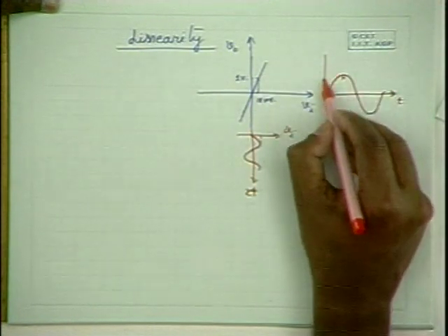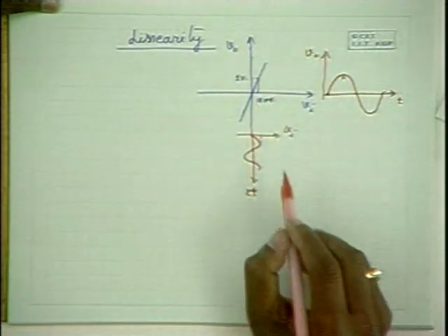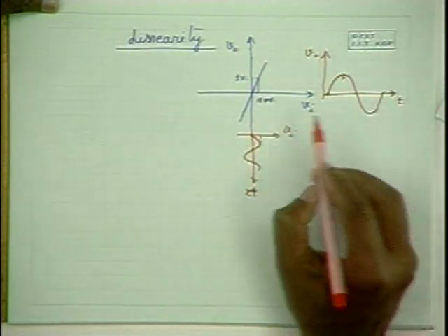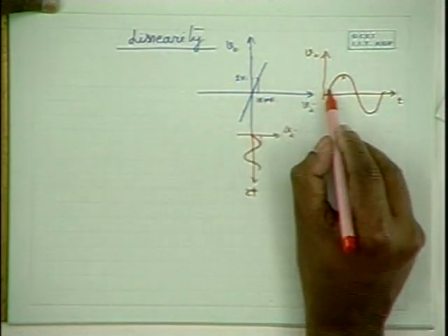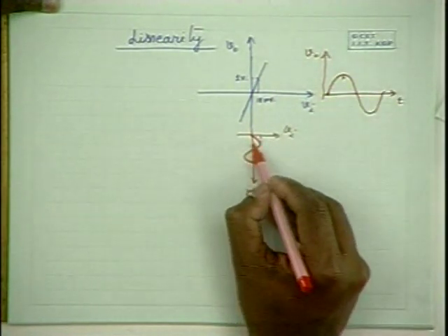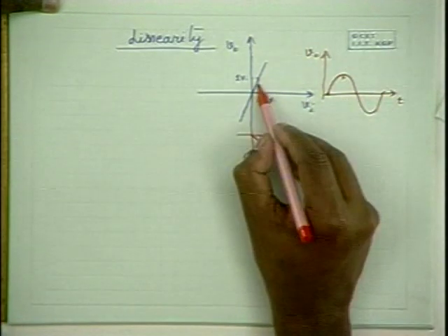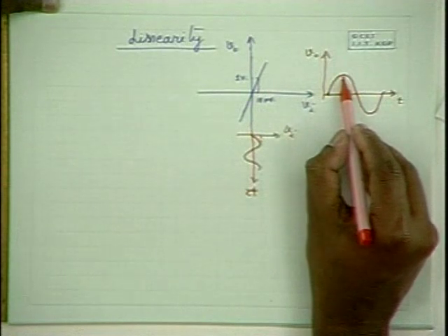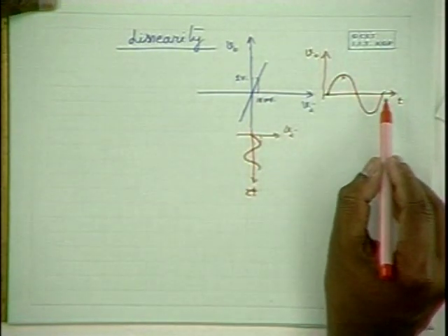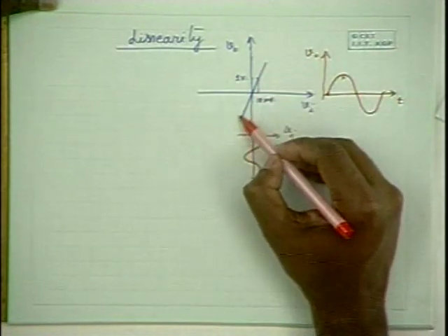as a function of time. And this is the V naught scale, and this is the Vi scale. I'm introducing time here and taking time here. For any input, I get the particular output, and I reproduce it at the respective times. Therefore, for any input voltage, I can find the corresponding projected output voltage, and I can find the output voltage plot. Now, this would be an exact replica of the input if this is linear.